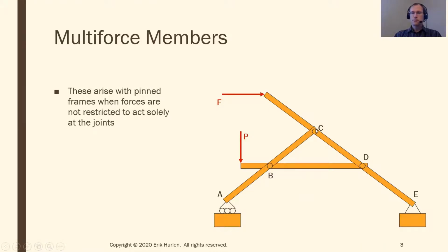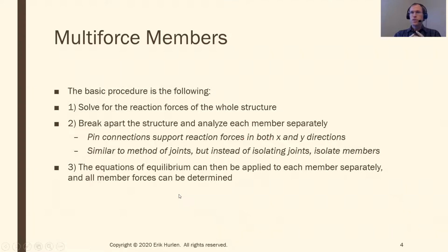Similarly, at pin C, this other angled member can be either pulling or pushing on member ABC. And so there'll be some external forces, again external to member ABC, CX and CY, that come from this other member. And so once I break that member apart, I can then do statics analysis, use equations of equilibrium on that member. I do the same for each other member. So again, in the previous situation, there are 3 members. Break those apart into 3 different structures essentially, and do rigid body analysis on all 3 structures. And that should give me enough equations to solve for all my unknowns.